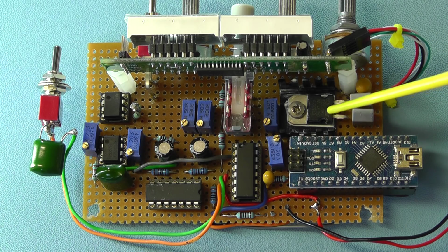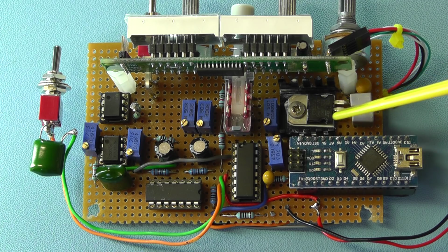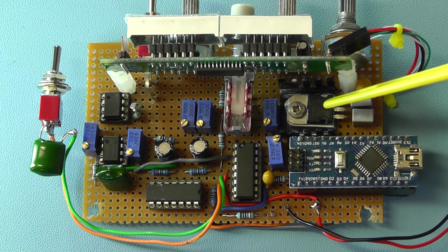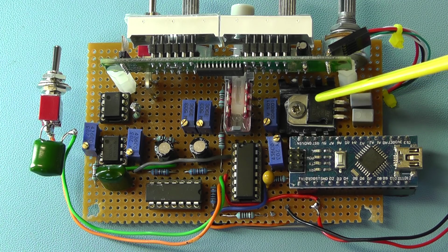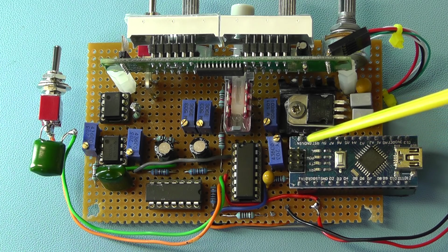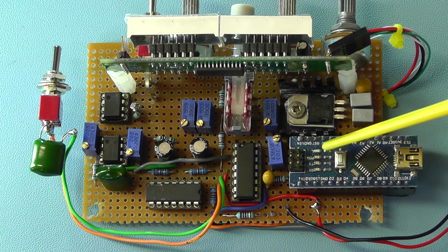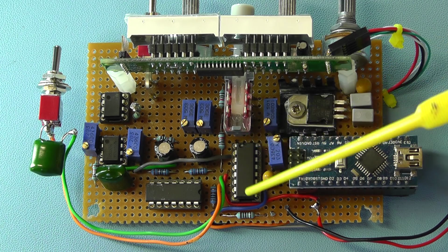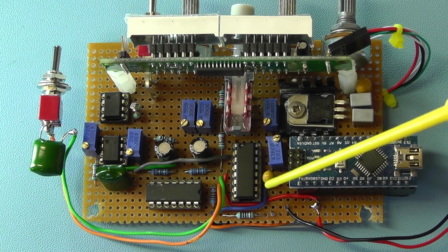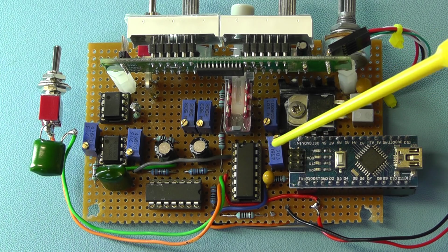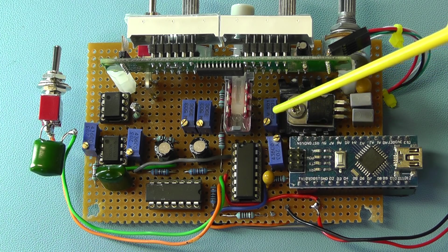Down there you can see I've put the 5 volt regulator IC with its associated capacitor, and I put a small heatsink on that. I'm using a 1 amp 5 volt regulator there. The Arduino is socketed and sits just on the edge of the board and overhangs slightly to give us access from the slot in the casing. The chip there, that's the main function generator IC, the XR2206, and the associated presets there for setting the symmetry and the sine wave shape.